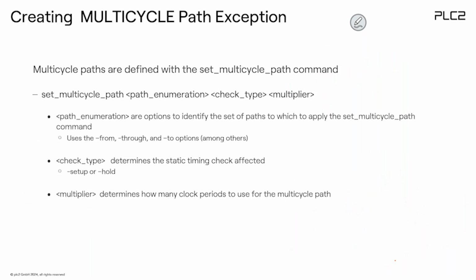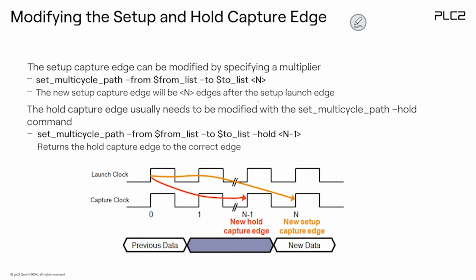So in this case, we can create a multi-cycle path. We say set multi-cycle path from A to B, and you don't define a time value like 10 or 20 nanoseconds. You always define the number of clock cycles. If you don't use the multi-cycle, the data captured here must be captured at the next flip-flop on the next edge, so you have one cycle of time. But if you say I have a multi-cycle of n, then you are saying don't capture the data here, just shift it to the new point, and this will be the multi-cycle.